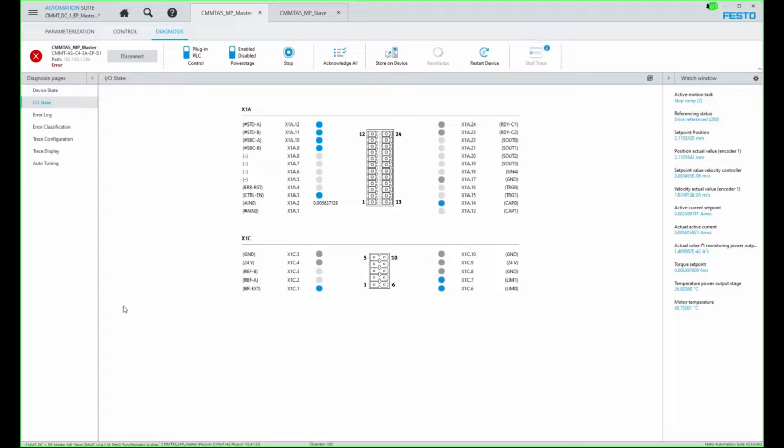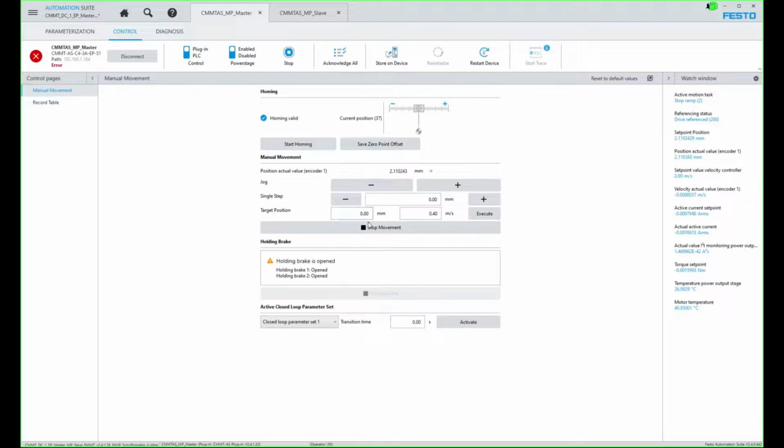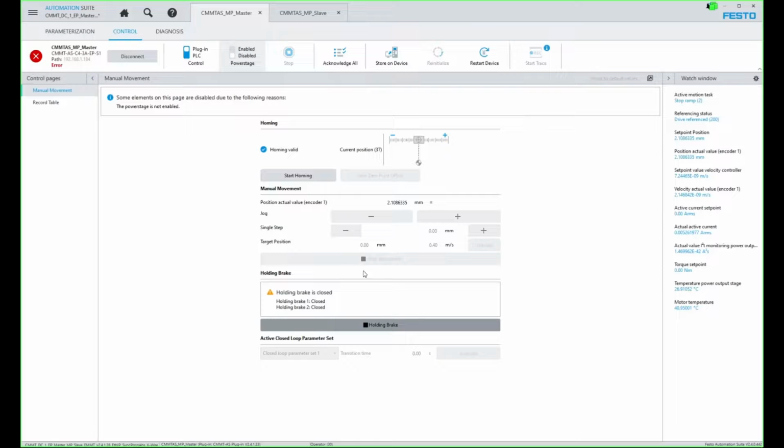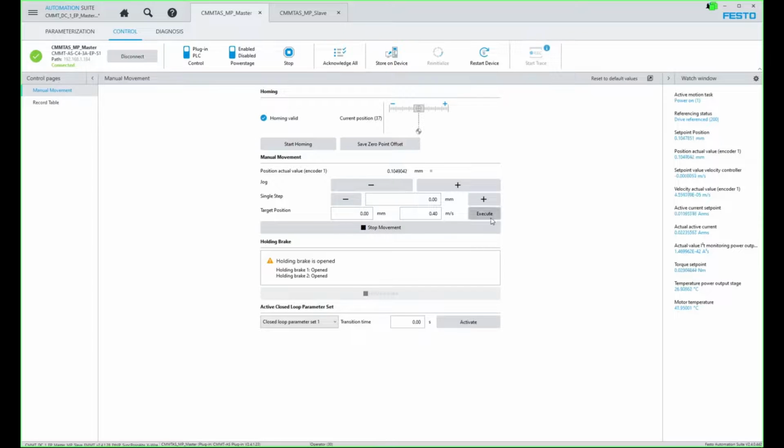Right now, because we're in the commissioning stage, this fault cannot be reset, because until we change the position, we're stuck. So at this point, you can disable the controller, do this, and then move this back to 0, so that we're within a tolerance of whatever the tolerance is. Now we've reset the fault. We put this back, and I'm simply going to go back to 0. Okay, we're back to zeros.